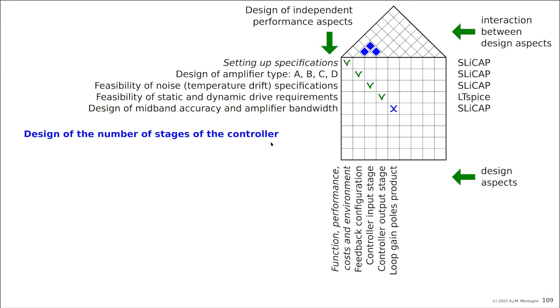So what we have as a degree of freedom, if we don't have the bandwidth with our two stages, is another degree of freedom, which is independent of what we already did, because we selected the CS stage for the input stage and for the output stage. It means that they have the best nullor approximation for those stages, and the distortion will mainly be determined in the output stage, and the noise will mainly be determined by the input stage.